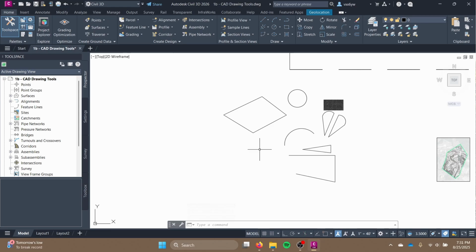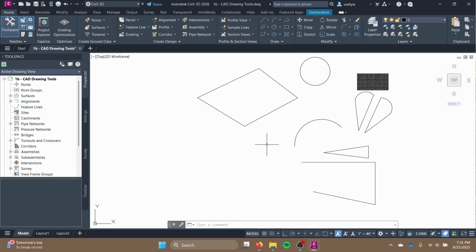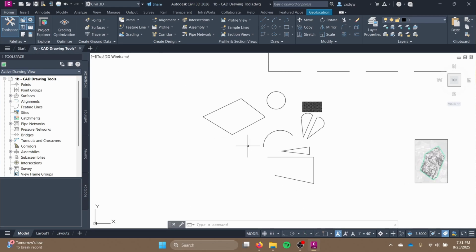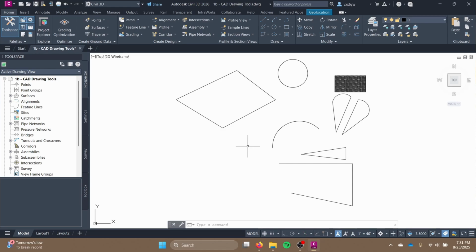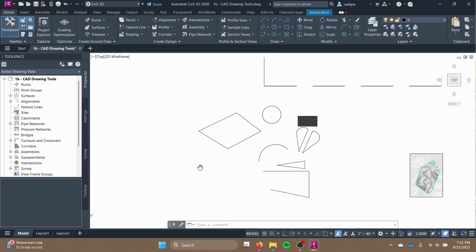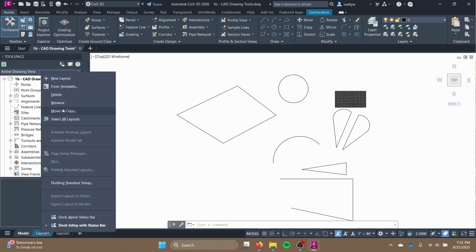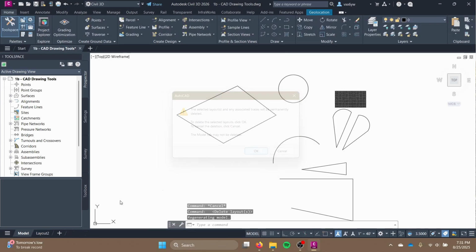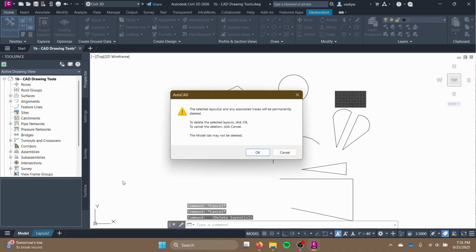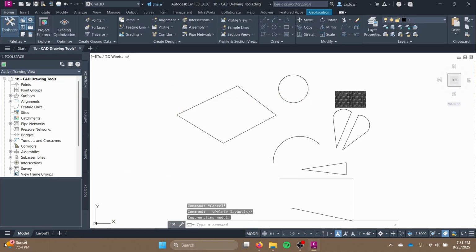All right, now to get to the main point of this tutorial being the plan sheets. Plan sheets are how engineers communicate their designs. We don't use blueprints in civil engineering, but we do use plan sheets, which are effectively the same thing, just not blue with a grid on the back. So in a previous video, I mentioned these layout tabs, and while they're great, they're kind of hard to use and don't have the template that we want. You can keep them there or delete them, either is fine. And instead, we're going to create our own.